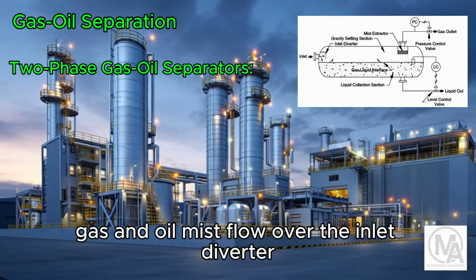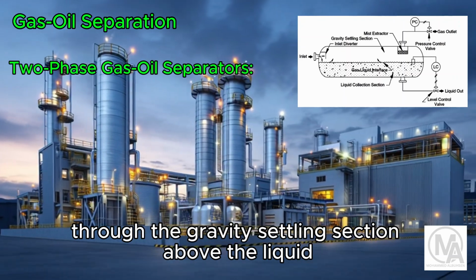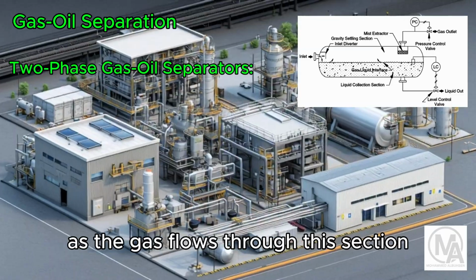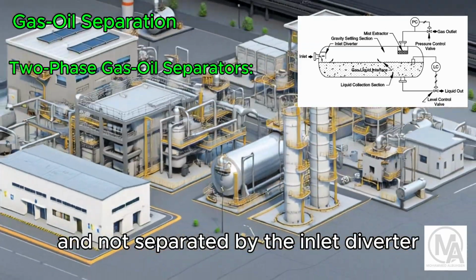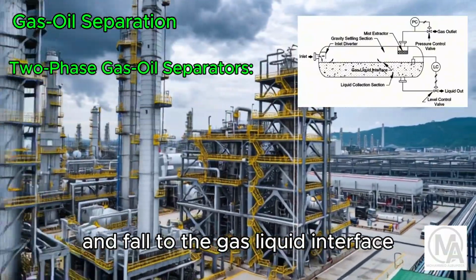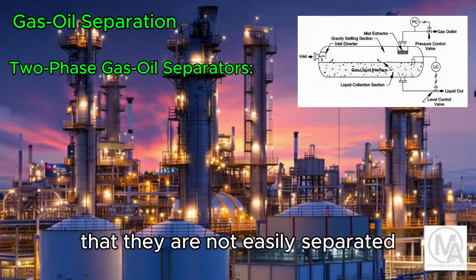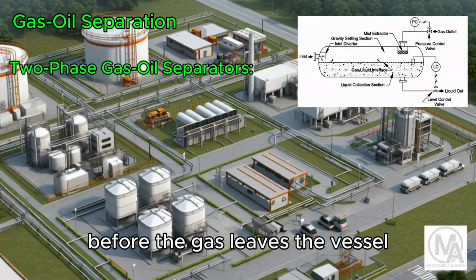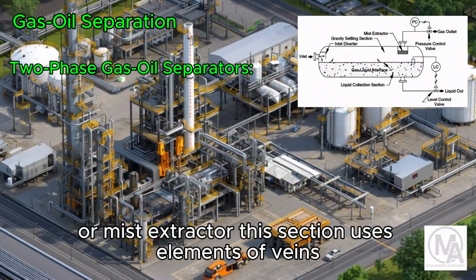Gas and oil mist flow over the inlet diverter and then horizontally through the gravity settling section above the liquid. As the gas flows through this section, some droplets of liquid that were entrained in the gas and not separated by the inlet diverter are separated out by gravity and fall to the gas-liquid interface. Some of the drops are of such a small diameter that they are not easily separated in the gravity settling section. Before the gas leaves the vessel, it passes through a coalescing section or mist extractor.